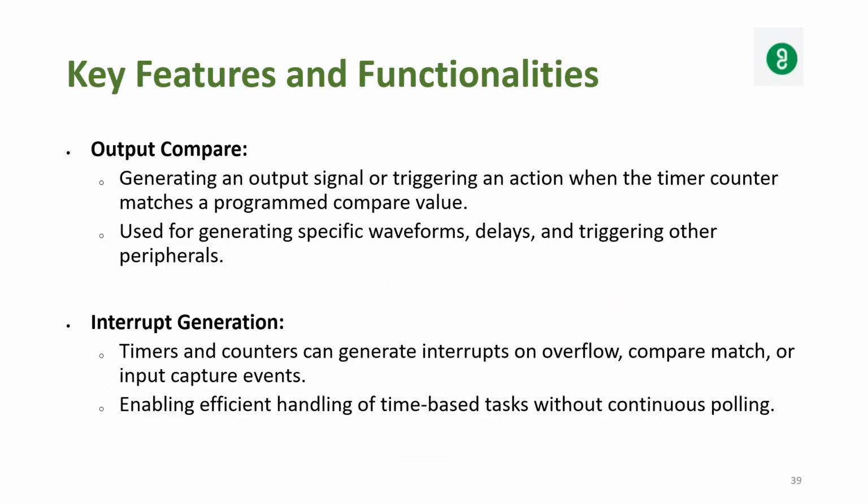Output compare. It changes the output signal or triggers an action when the timer counter matches a programmed compare value. It is used for generating specific waveforms, delays, and triggering other peripherals.